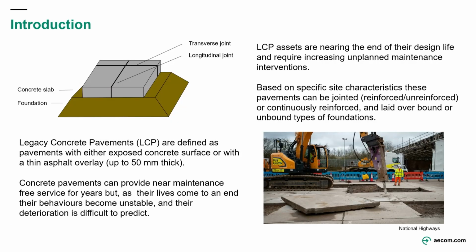As for today, we are looking just at legacy concrete pavements, which are defined as those pavements with a surface of exposed concrete, or with maximum 50 millimeter of asphalt layer on top. We can consider these pavements as a single group because the asphalt overlay really doesn't make a contribution to the structural behavior of the concrete. So we can model them together.